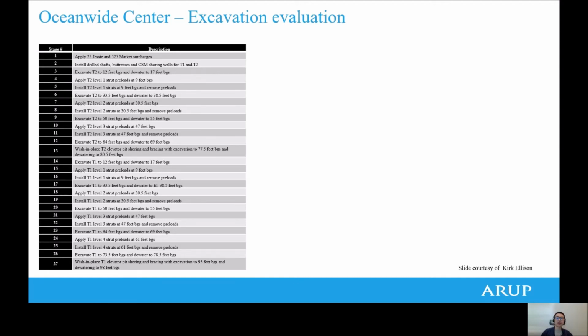The excavation in reality is done layer by layer for the soil, combined with the dewatering process where the water table is lowered. And after each excavation stage, the bracing or strut would be added with preloading.